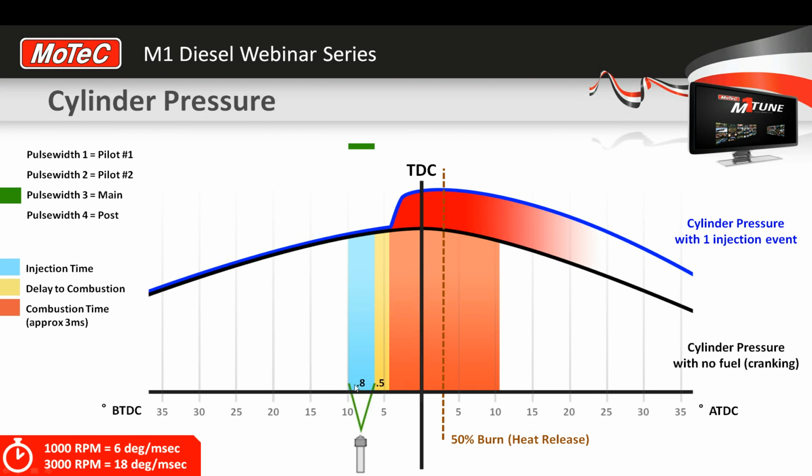This is almost the opposite of petrol, where your injection timing numbers go up as your pulse width goes up. Fortunately, if we want to add fuel in a diesel, we have two options. We can increase fuel pressure to increase fuel flow. So rather than increasing our pulse width, we can increase our fuel pressure enormously from idle. We could have an idle fuel pressure of something like 40 MPa, but we could potentially lift that to 220 MPa. That's significantly higher.